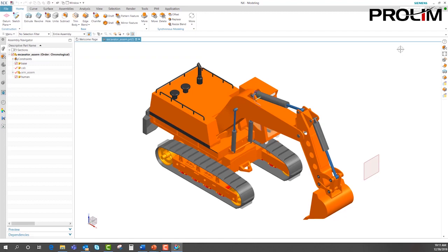So if I hit a block and I go and do a chamfer, next time I hit a block, it will predict that I want to chamfer next. If I hit a block and a hole, it will then put not only the chamfer, but also the hole as my prediction. This is done by statistics in the background, and it learns as you continue to use the system. Now this is an add-on, so you may or may not have that add-on. It is a very nice feature that allows you to quickly go in and redo your steps over and over without having to reset new toolbars.